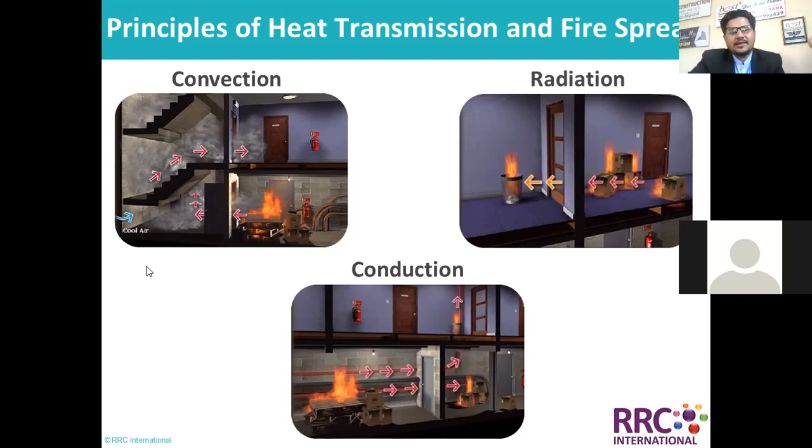Now, along with that prayer room, there was a drainage system, maybe 2 feet, 2.5 feet, covered with concrete. And the moment they moved the fire truck back, near that wall or that prayer room, the tires went down because the concrete broke up, because of poor material or poor lifting capacity, not designed for a fire truck, of course.